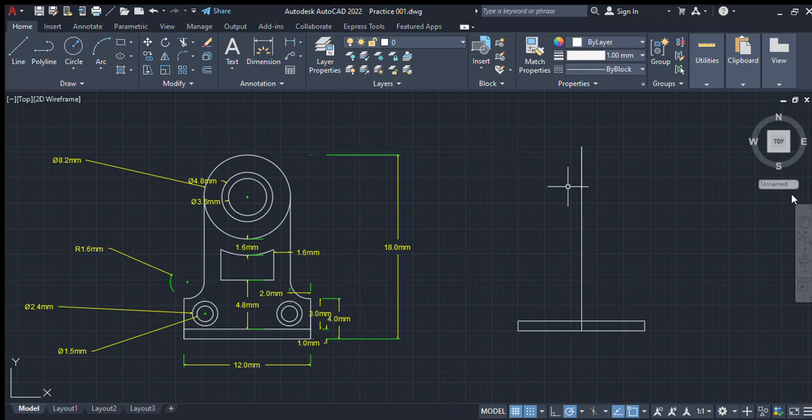We are now going to go to our radius and pick diameter. This diameter, look for the 4.1. This is the 4.1. So look for 8.2. Now you are going to press 8.2. Enter. I hope you get what I'm trying to say.